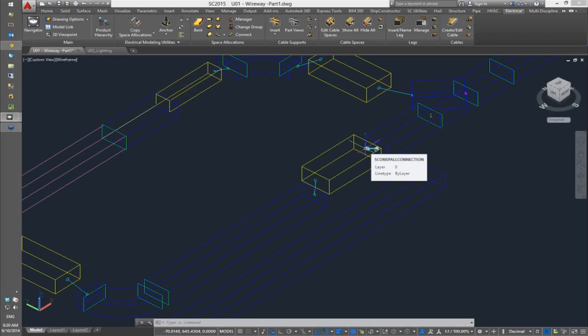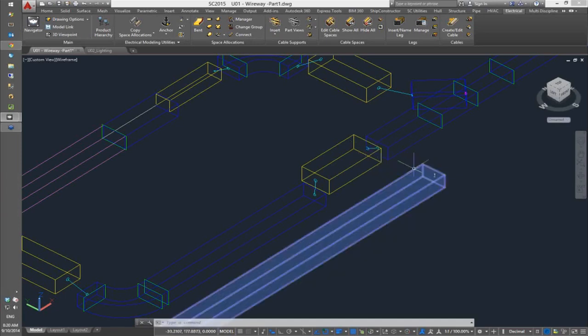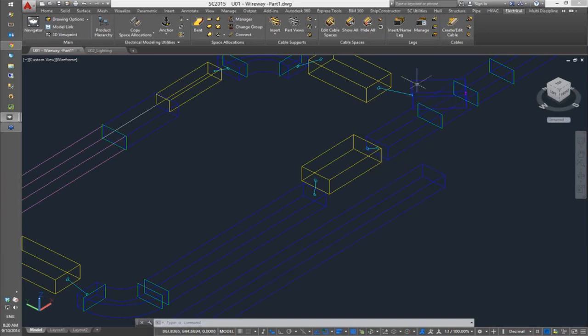And these allow me to make these connections across these networks without having to do any awkward modeling. When you're routing cables, any cables that are routed across those connections, the length of that connection is included as part of the length for that cable. So we do factor it into that.